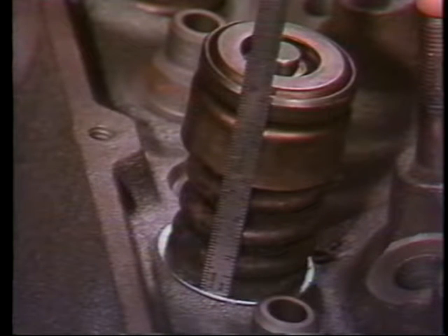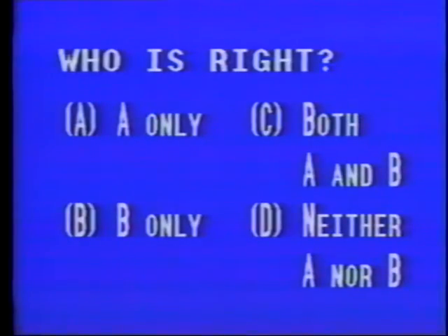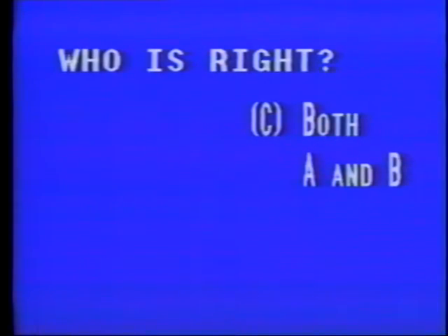The solution is to place a shim under the valve spring to restore it to the proper installed height. Valve shims come in different sizes and thicknesses to fit many applications. The correct answer is response C, both A and B.